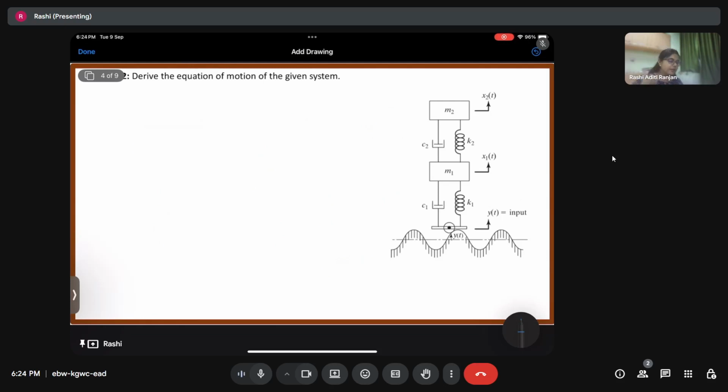Usually, when a system is of this type, wherein we have excitation involved, we prefer using the force balance method, right? Because if we talk about the energy method, therein we consider only the conservative energy. For a non-conservative system, we have the modified Rayleigh dissipative potential, but we don't know how to deal with forces. However, we have Q1 and Q2 that we introduce in case of the Lagrange equation. So basically, we were finding out the total energy and differentiating it, but it was applicable only for a conservative system. When we come to a non-conservative system, we were using the Lagrange equation, right?